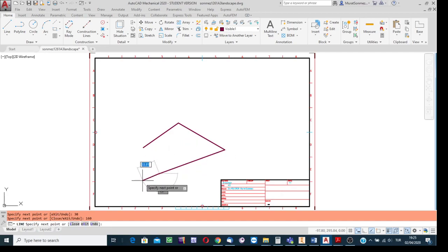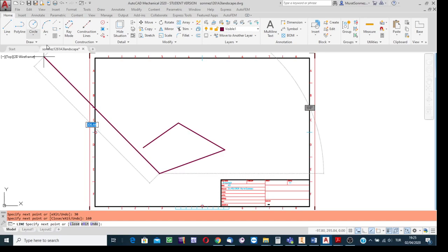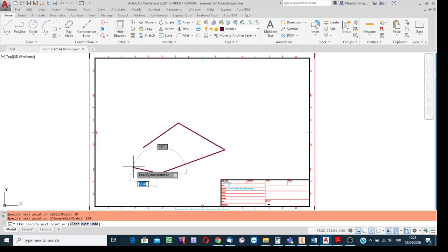Okay, and then, well, you see, this is not a polyline creation process, it is a single line creation process, but you see it is possible to create the lines in sequence. Preceding line and then following, preceding, following. But if at the end the region bounded by those lines is going to be indicated for applying the extrusion process, for instance, well, the region is to be defined as a region.